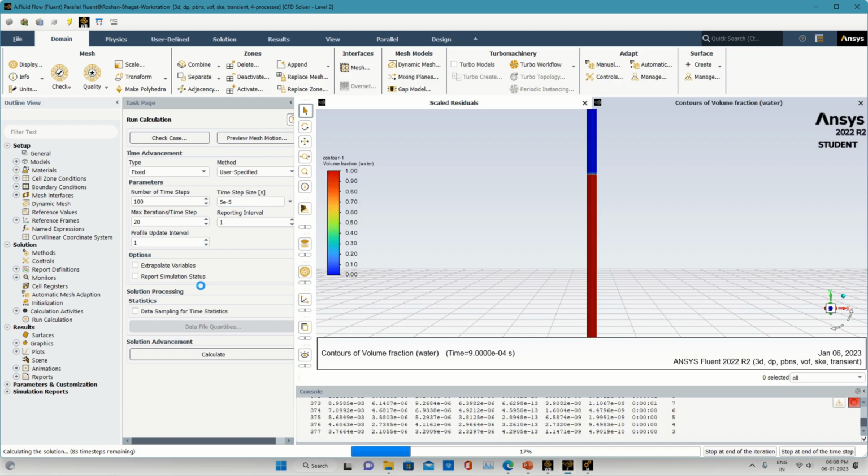So if last time the error occurred at 999 as a time step over here, we'll just check whether the same problem occurs or not. One thing which you might have observed is we had taken quite a fine mesh size earlier, because of which the time required was quite more. Here the time has been considerably reduced.